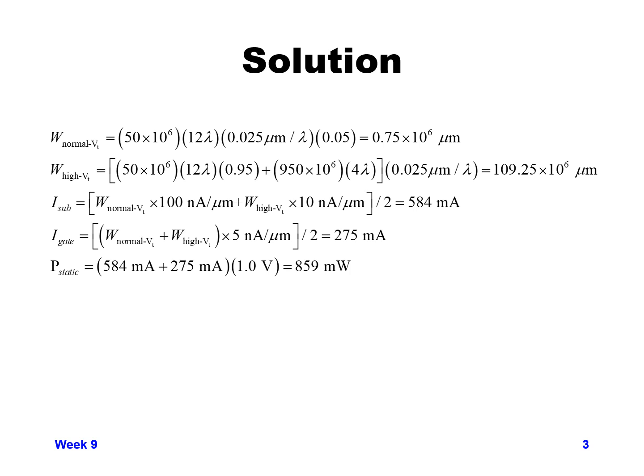The reason for the division by 2 is a key point: for each gate, whether it's high or low, only on average half of the transistor width is leaking. Keep in mind, for example with an inverter, if the inverter is pulling low, the NMOS device is fully turned on, so the NMOS device isn't leaking.